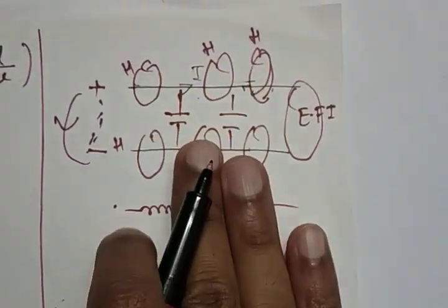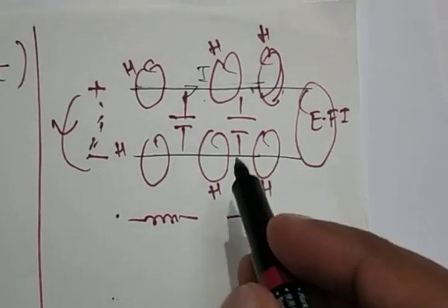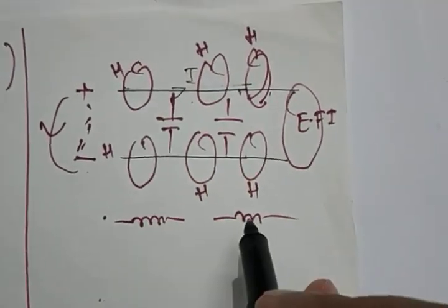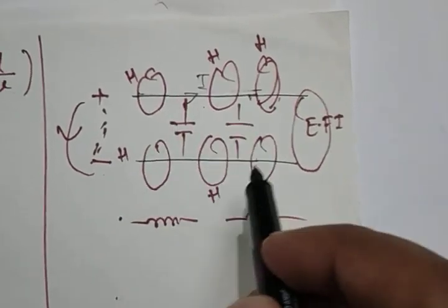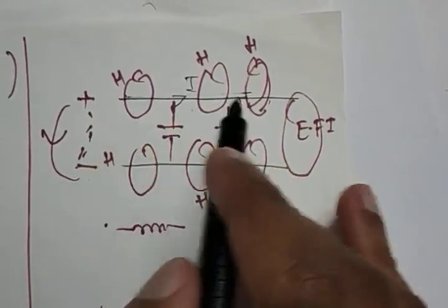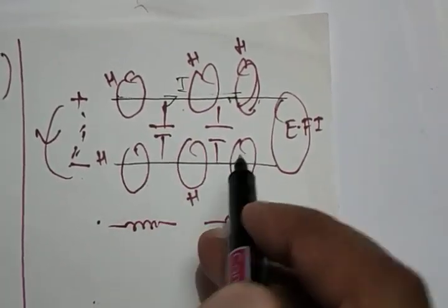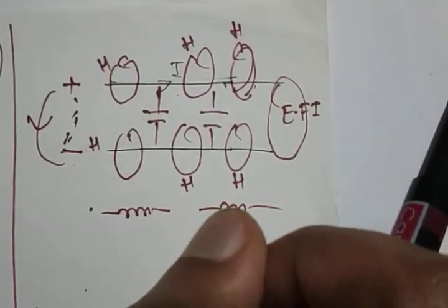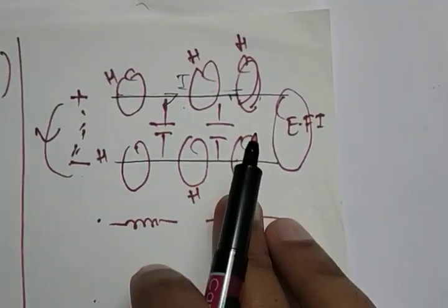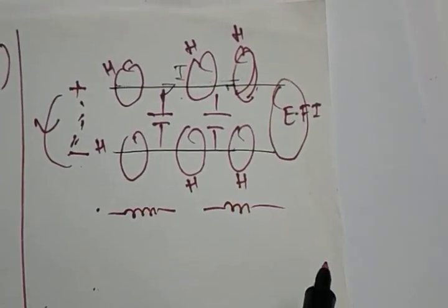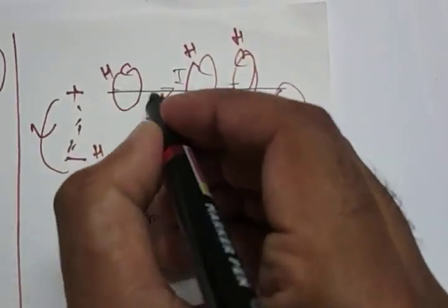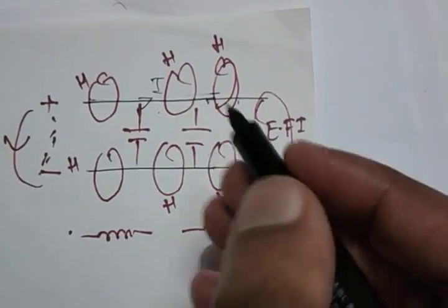You have to keep this thing in your mind, that there is no actual capacitor or actual inductor, but due to the presence of electric and magnetic field, and they are considerable because the length of the lines is very huge. It is not a small circuit. These are meant to have kilometers or meters in length. These are very lengthy lines. So along with these two parameters, we will also have the internal property of material.